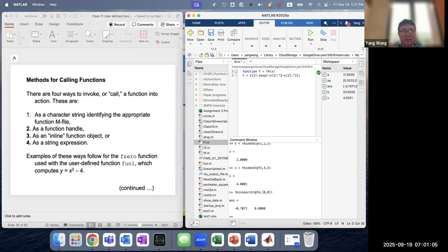Of course there are analytical solutions, but if there are more sophisticated systems for which we cannot find the analytical solution, then we will use these functions to find the minimum. Or we can also find out at which time the BOD level reaches a certain level, right? Say the BOD or organic concentration reaches 1 milligram per liter. If you have the model, you can just list the BOD equation minus 1 milligram per liter and set that to be 0, right?